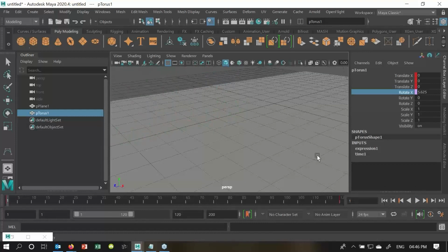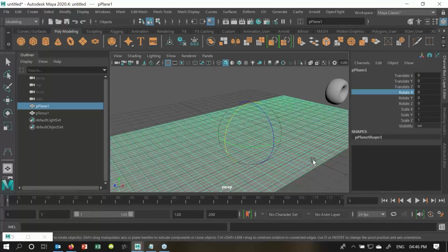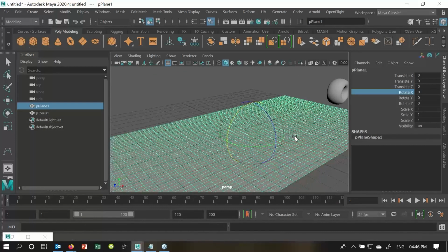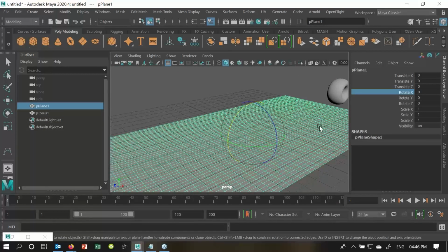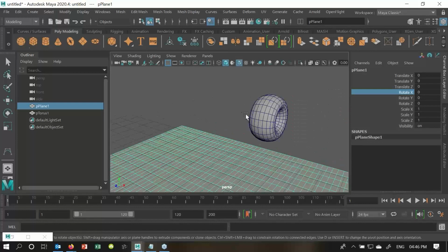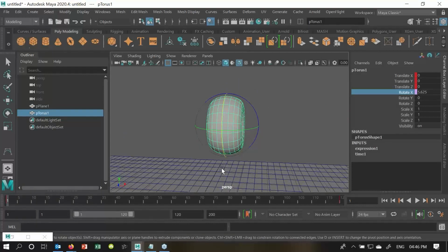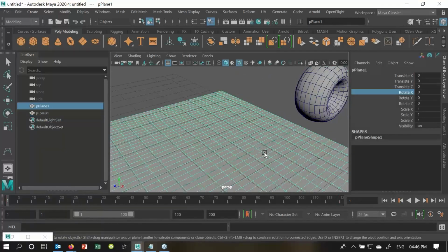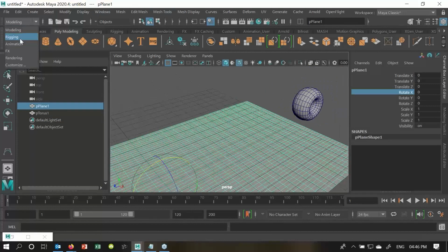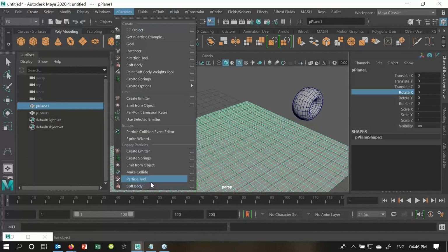If I want to do that, first of all I need to make this a soft body. Now why soft body? If you see over here, I want that whenever my tire is connecting with this particular area, some kind of trace movement has to be done, correct? So I'll select my object, FX, and particularly here we have the soft body.